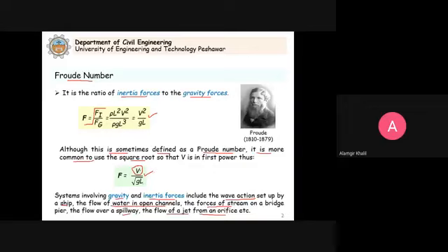So if you calculate from Froude number and you fully understand that in that case the Froude number needs to be considered, the results will be realistic. But for example, if you apply the Reynolds number, there V is also present, and you want to calculate the velocity in the prototype, then in that case you may not get realistic results. So that's why understanding of the basics in order to use these concepts is very important.